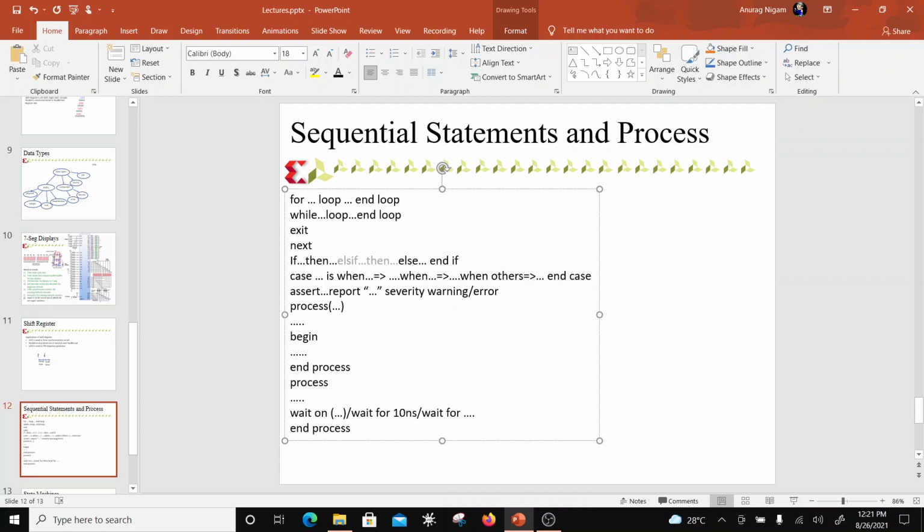So this is kind of complementary to polling. Polling is where the master polls something, while here it's a different form of polling where the slave says, I have a flag and I need to do something. Again I have a flag, I need to do something. So basically the roles are reversed.